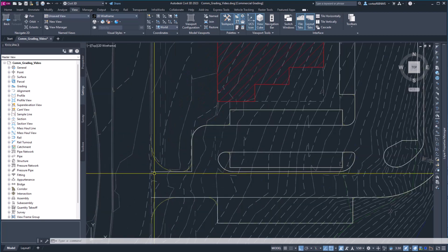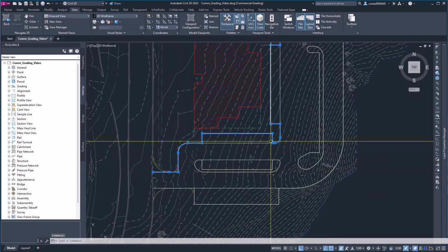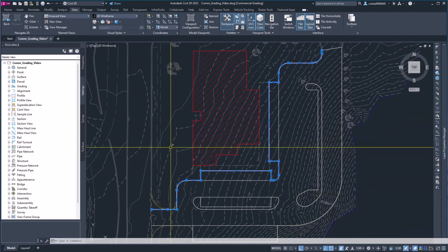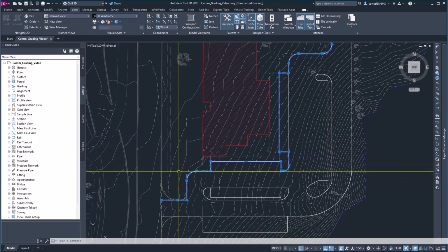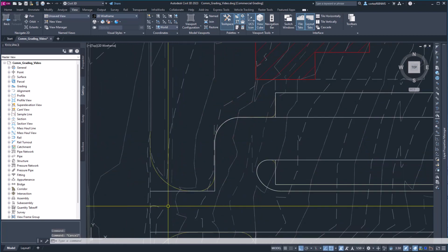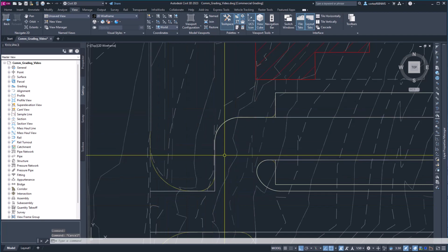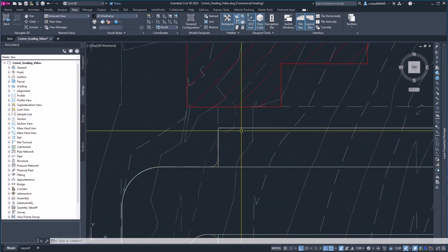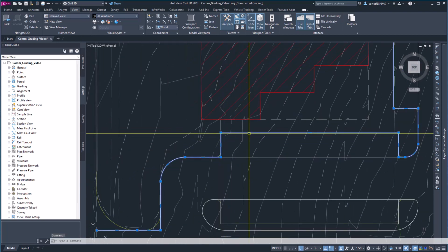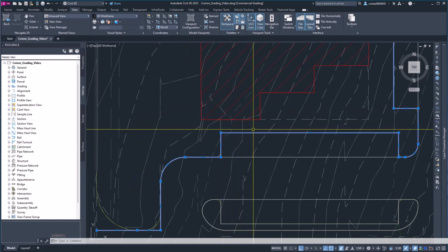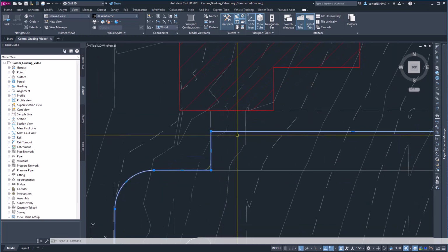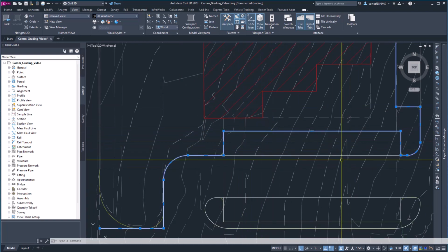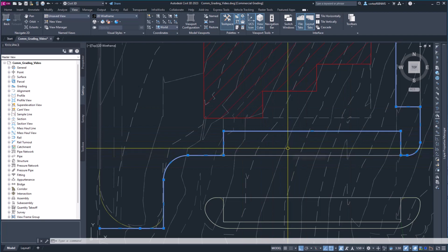So how do I do it? You can just go through, maybe create a feature line at a 0 elevation and then start throwing elevations on it. What I like to do for simplicity's sake is, as you create feature lines, obviously you're going to have a bunch of data. A lot of times you're not going to want a point somewhere, and let's say this here is a walkway up to the building. When you add this point here, it's going to add a point to your feature line and it's going to have to register all that.